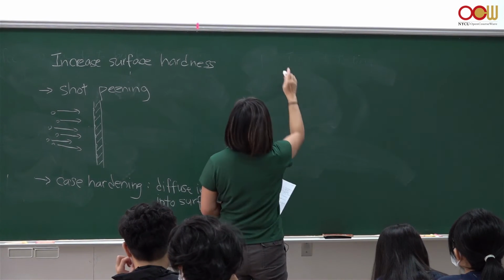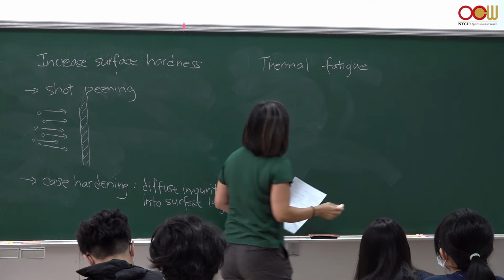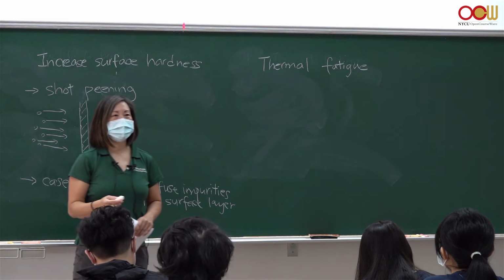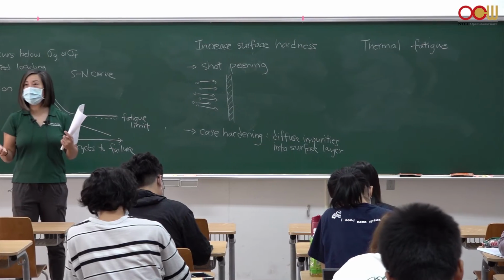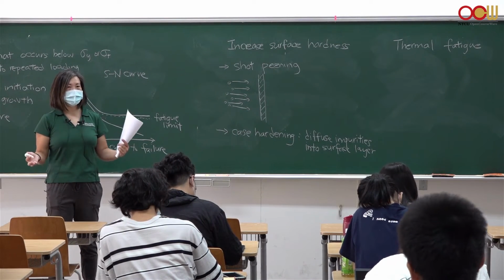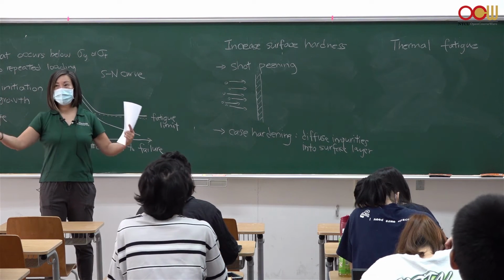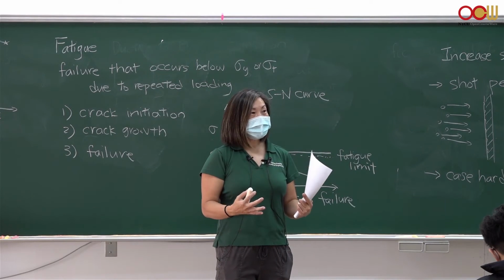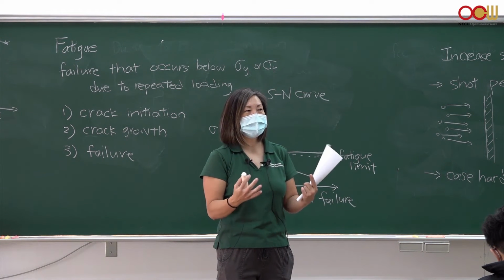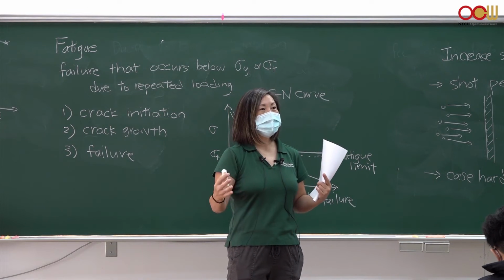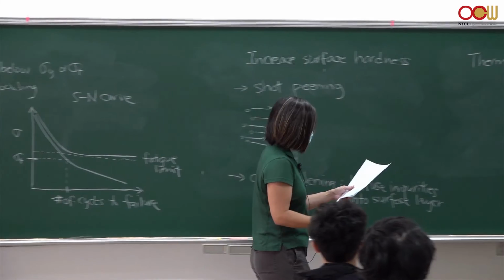Another, related way a material can fatigue is due to temperature changes. Let's say you have a material with no stress on it, but it undergoes large temperature changes, hot, cold, hot, cold. The material will expand, contract, expand, contract. If it's doing this, then it's like having a stress on it, and so it could experience fatigue. So thermal cycling can also create fatigue.